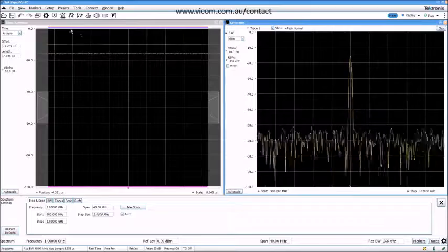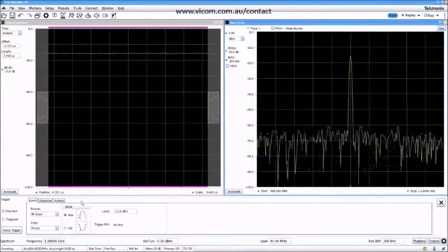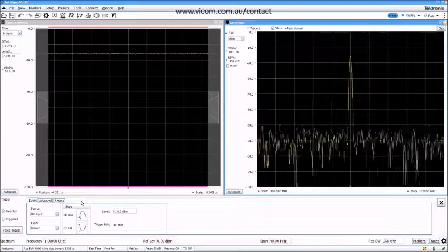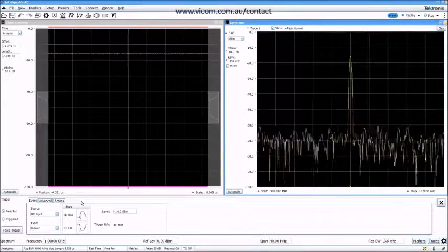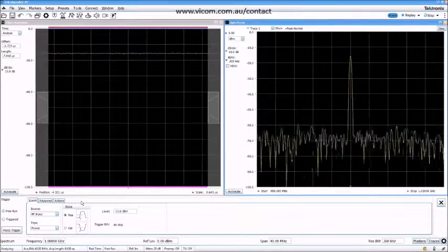The Trigger button gives you control of the hardware trigger for your spectrum analyzer. This allows you to set a signal condition upon which you want the analyzer to capture data. There are many trigger types and options depending on which instrument you are using.